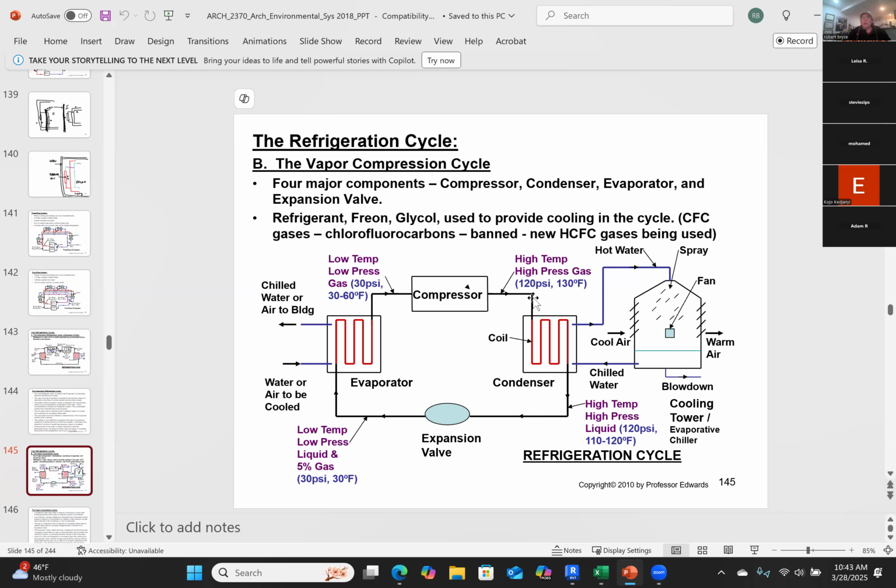So what's happening here when we put this compressor in here is that it's absorbing all of the heat and putting it into this coil or this pipe, and we blow that heat outside and then bring that high pressure gas across here until we change the pressure to a low pressure. We expand it, it's cool again, and then we can extract the coolness from that gas. The change in state in this case in air conditioning is in the pressure of the gas.